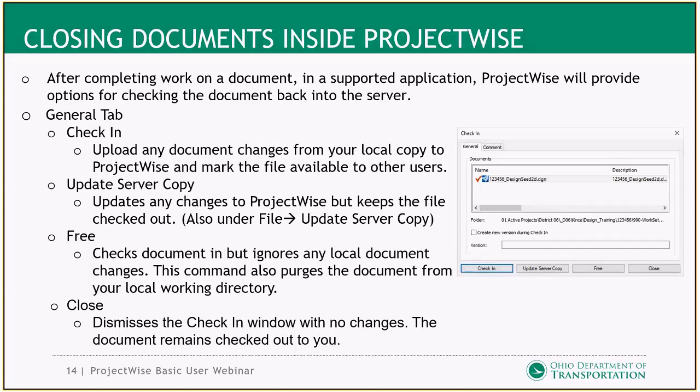The first option is check-in. What check-in does is it checks the document back into ProjectWise. That red check mark goes away, the lock goes away for other people, and it saves all the changes that you did in the ProjectWise environment.